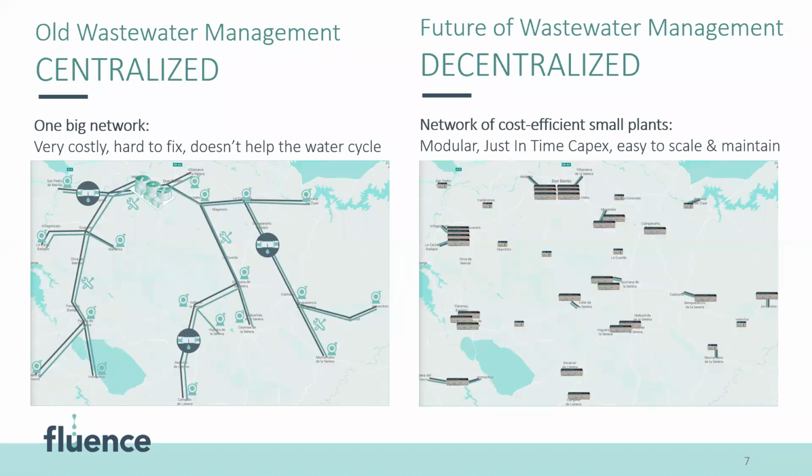They're different in many aspects, and just by visual impression, it is evident that the decentralized plan is definitely more flexible, as it could be installed gradually one by one, as opposed to a central plant that is essentially built all at once, and very sustainable for local treatment and reuse.